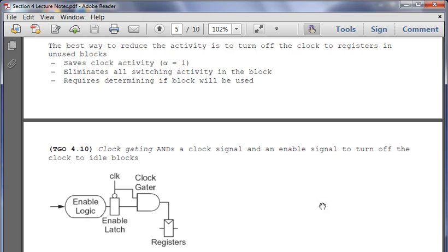But the benefit is that the enable logic matches pretty well with the different stages. Instead of doing all of fetch, decode, execute, memory, and write back, if you're doing an R type, you just do fetch, decode, execute, write back, because you're not accessing data memory. So you're only executing those. The enable logic matches very closely with the control signals that you need, so the ones that you don't need just turn right off.